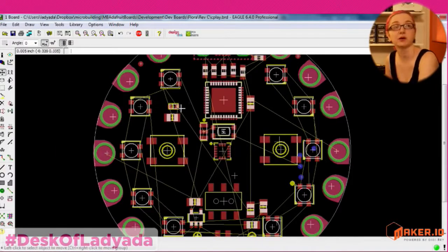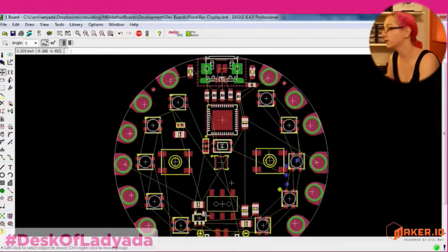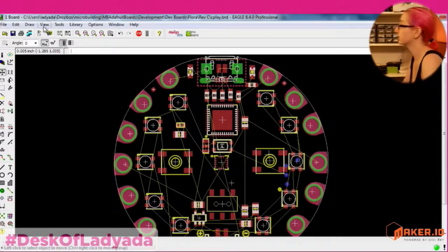I only have to pull a pin over here. And then likewise, for the Neopixels, the pin that's going to control these is going to be from over here. So I can make a straight shot over here and then have the data line go around. And then the buttons, try to get them to come in from the corner. It's going to be a little harder for the components down here, but as much as possible, try to pick the pins and place the components nearby. It just makes your routing a little easier, makes your life a little easier.